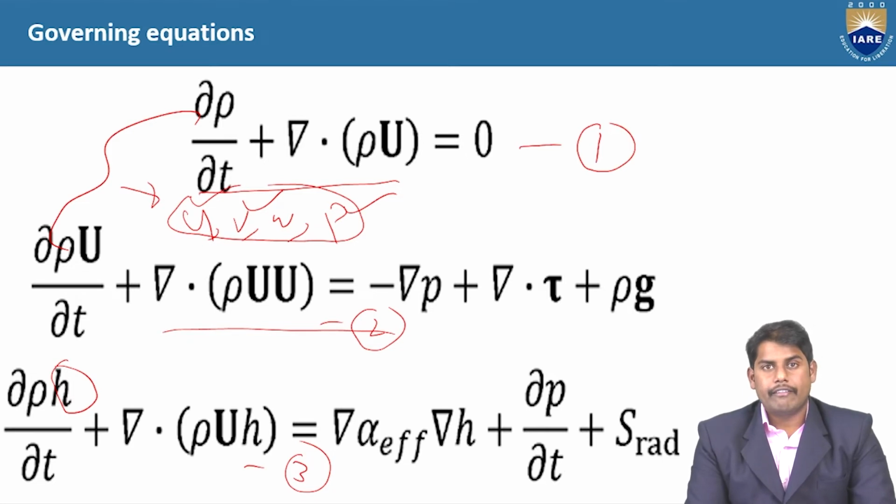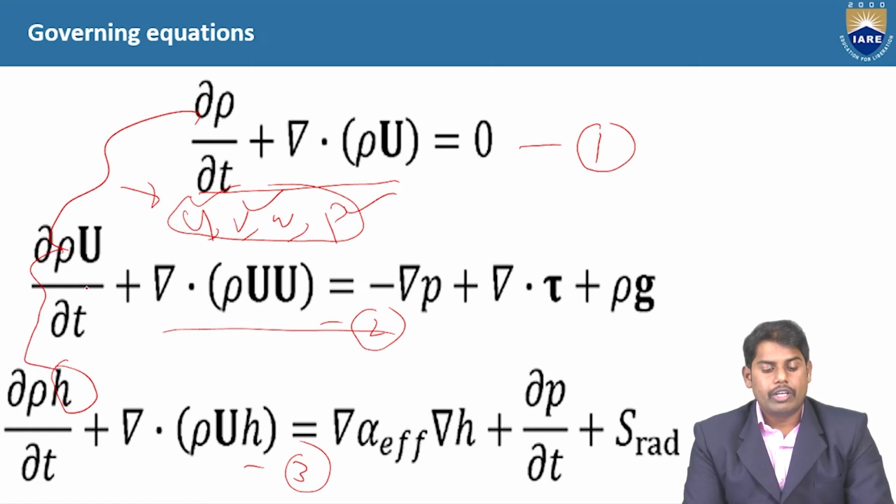When we are solving a compressible flow equation or a heat transfer problem, we need to take all three equations into account: the continuity equation, the momentum equation, and the energy equation.